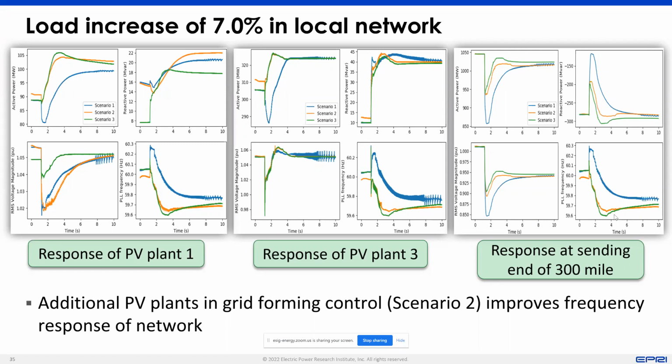So it comes down to varying degrees of stability. Once you go from an insufficient amount of voltage control and frequency control, your system collapses. Once you have that sufficient level of voltage control and frequency control, it's not that there is no additional benefit. There is a small incremental benefit, but after a point, there's only so much more voltage control will do because you already have system firming capability brought in, which means the system has enough capability to respond and react.